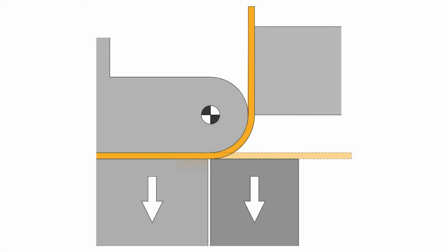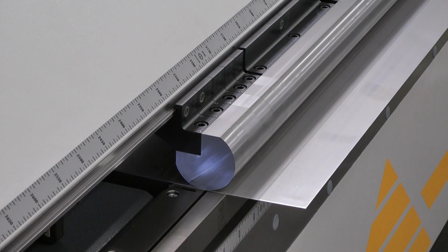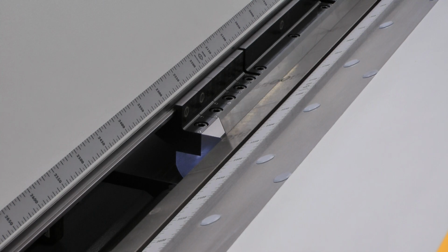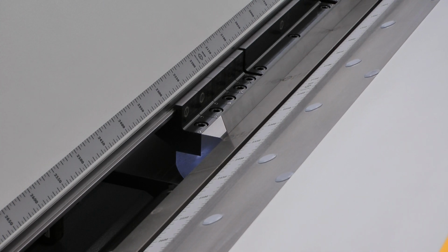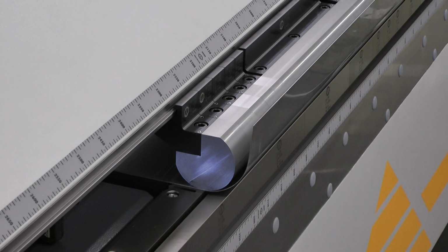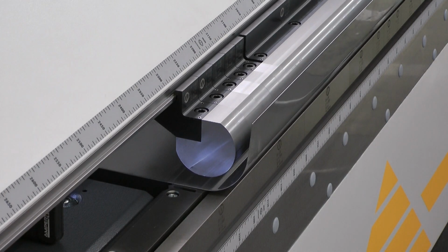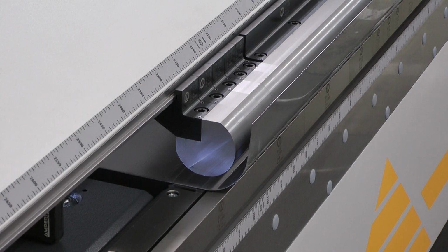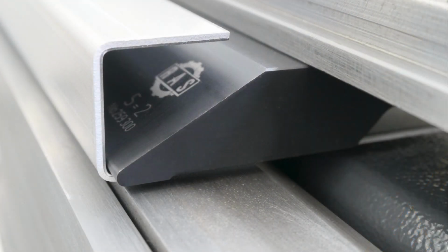In this case, the machine must be able to position the lower beam and folding beam to the proper pivot point. The folding motion pulls the metal around the radius tool. Due to strong material springback, significant overbending is required. Before the folding beam swings back to its home position, it moves away from the curved radius to minimize scratch marks on the surface.